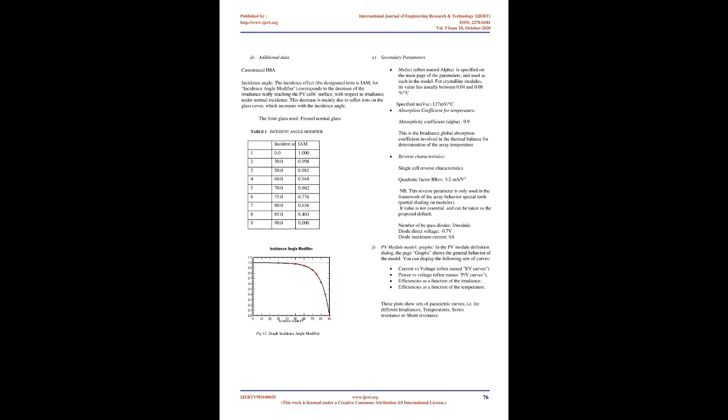B. Orientation. The orientation of the solar panel decides the tilt angle and the azimuth angle. There are various field types available. For this project, seasonal field type is used. Due to the sun path and geographical location we kept a summer tilt of 16 degrees and winter tilt of 47 degrees and because there is no elevation the azimuth is 0 degrees. This is kept to ensure minimum amount of loss during the summer and winter months.